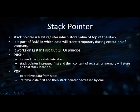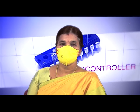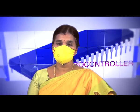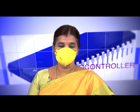The stack pointer is used to maintain program execution. When we use jump instructions, the program counter is loaded with a new address to switch over to. During that time the current address is stored in the stack, then the program counter executes the subprogram. After reading the return instruction, it returns to the proper place by popping the data from the stack. So, during jump instructions, the stack pointer plays a role in maintaining the sequence of program execution.